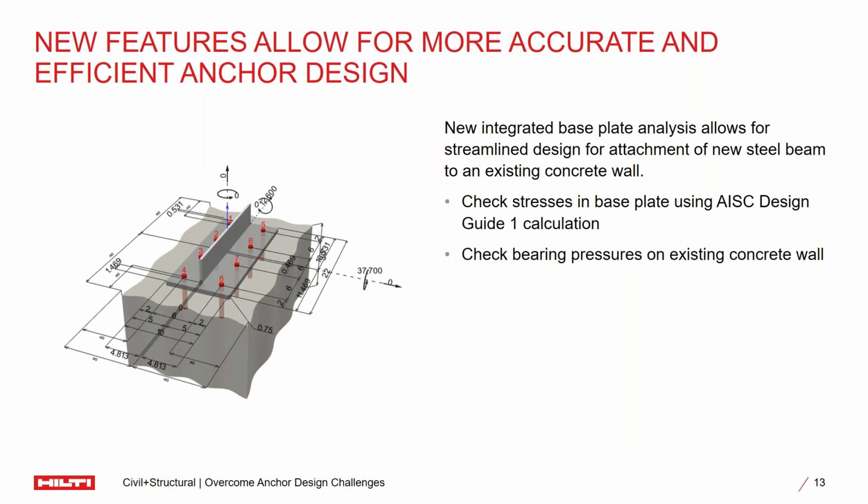More recently, I used the software to attach a new steel beam to an existing concrete wall using a plate and a shear tab. I used the premium features of the software to design, or check, the base plate for stresses based on AISC's Steel Design Guide 1. I also used the features in the software to evaluate these stresses on the concrete to ensure they were within acceptable levels.